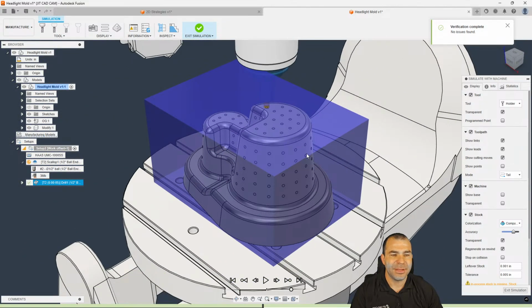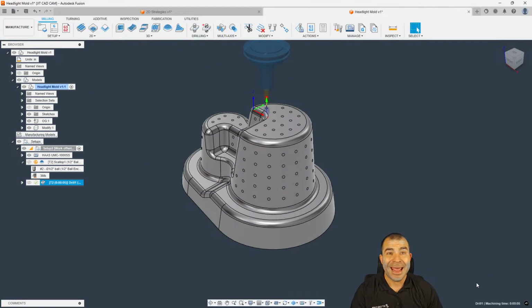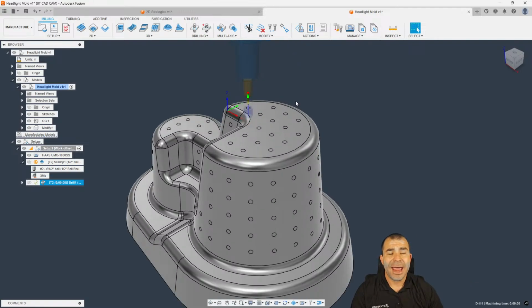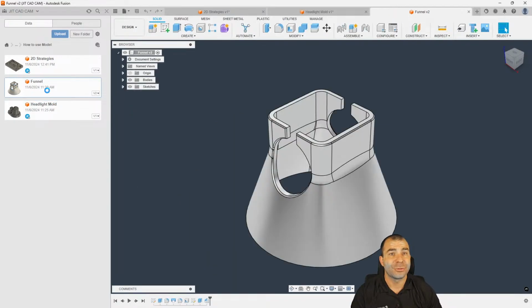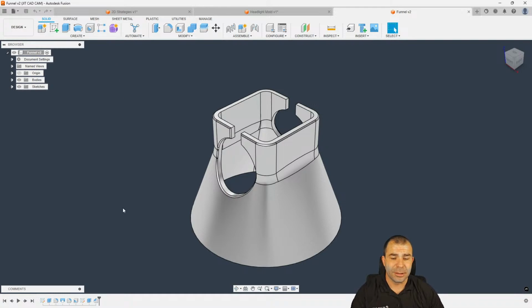So again, this is something to keep in mind, that you don't want to add these modified bodies or these manipulated surfaces at the setup level, substituting our original setup part, right? So let's look at one more example. Now this gets really fun when you have Fusion 360 and you're doing everything in both softwares. But the same rule applies if you're somebody out there using the new Deburr toolpath in the extension, the same rules still apply, right?